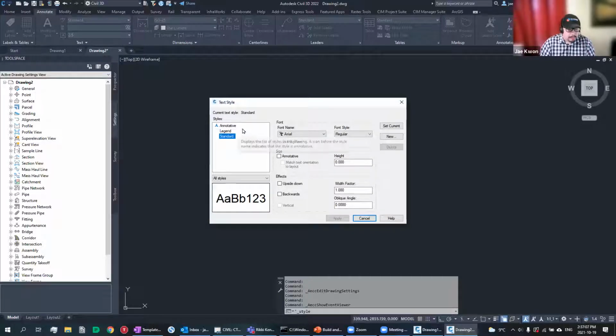There are a number of approaches you can take with text styles. Maybe you use standard styles like non-annotative. Maybe you use annotative exclusively. And maybe you use text styles that have preset sizes, or maybe you use ones that are just set to 0 and you set the size every time. I'm going to have to pick one approach or the other. So I'm going to take my favorite approach, which is to take annotative styles set at specific paper size heights. So that's what I'll do.